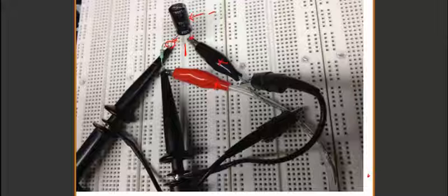And then when you are connecting the oscilloscope probes, make sure the two grounds are connected to the ground, which is the black. So the black one is the ground, and because I have a metallic extension, I'm able to connect the ground of the oscilloscope to this metallic extension, which is conductive. And make sure you're not connecting these grounds to another point. This is another common mistake I have seen from students. Make sure these grounds are connected to the negative side of the capacitor.